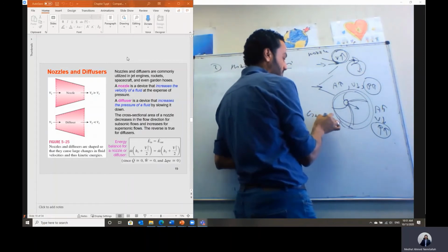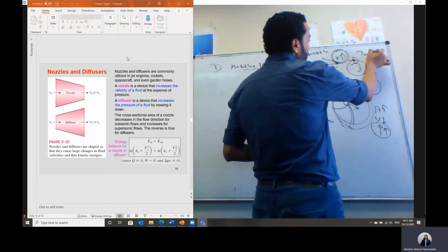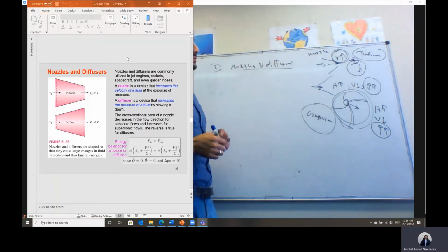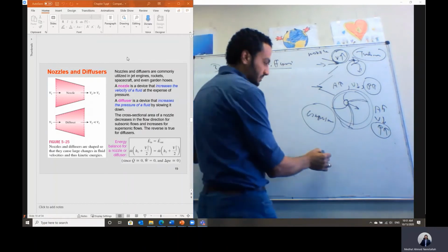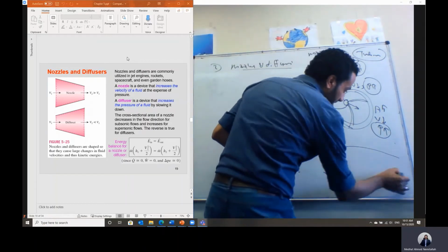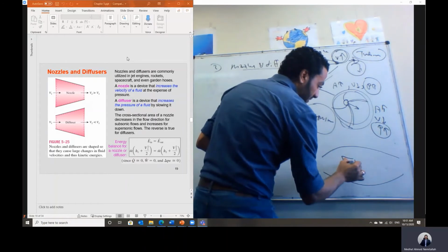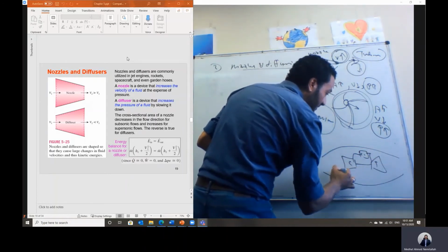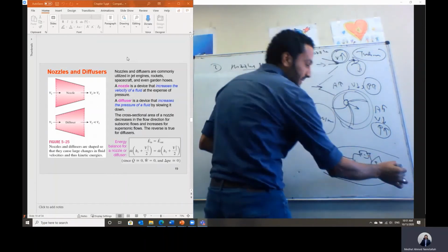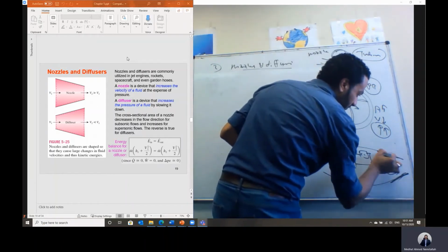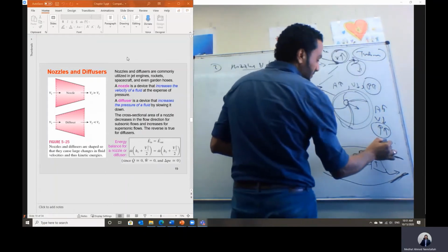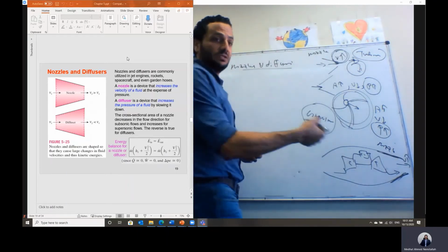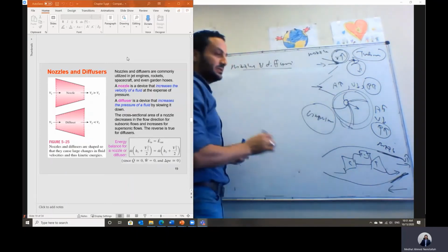This is in case of compressor, and this is in case of nozzle, accelerating the flow inside the turbine. And we said there is also another application, the jet engine. As we said, we have a gas turbine: compressor and turbine, and here we have the combustion chamber in between, and the gas is expanding inside the turbine. So the tail part of the jet engine takes the shape of a nozzle to accelerate the flow. So the flow will be leaving at high velocities. That's why we have thrust force in the reverse direction.